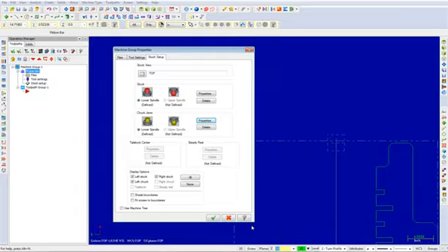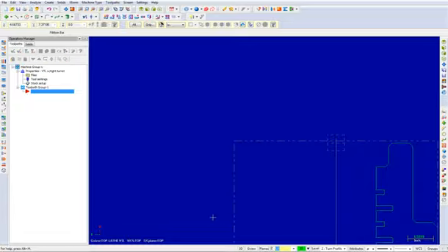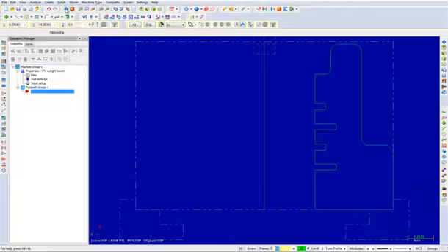Now, enable Fit Screen to Boundaries in the Display Options area. Select the OK button to exit the Machine Group Properties. You can now use the fit icon to fit the drawing to the screen. Your stock and jaws will appear as shown. In the next video, I will cover the parameters found to face, rough, and finish the part.